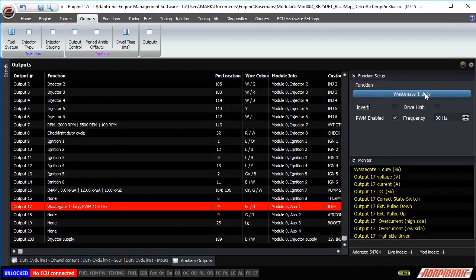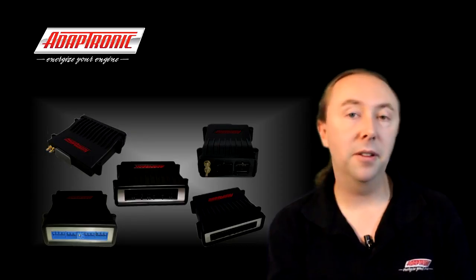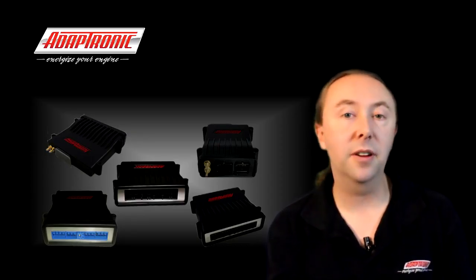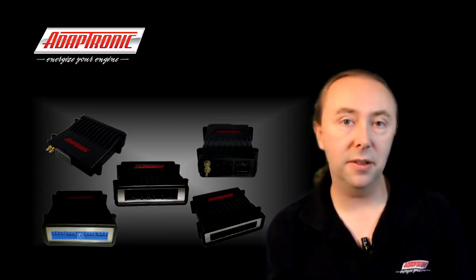And even though you see wastegate duty cycle 2 option available, the only reason you'd use it is on a dual wastegate system where you've got 2 separate controls and you're doing it closed loop. For example, on a 300ZX or a V12 where you've got 2 separate turbochargers and 2 separate inlet manifolds, and you need to control the 2 independently.